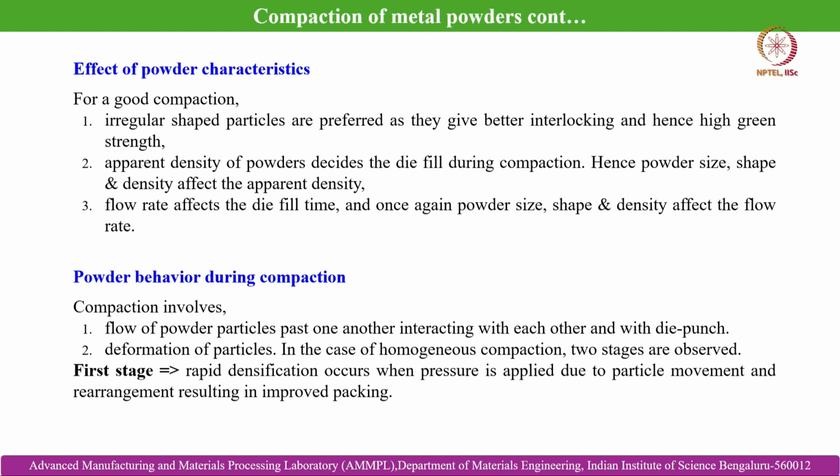But please remember, as I discussed before, that although irregular shaped powder particles give higher green strength and also higher green density because of interlocking, we are not intending to use the powder aggregate at the green state. In the next stage, that is the sintering stage, this irregular shape poses many challenges, that is pore formation, and also that weakens the structure as a whole.